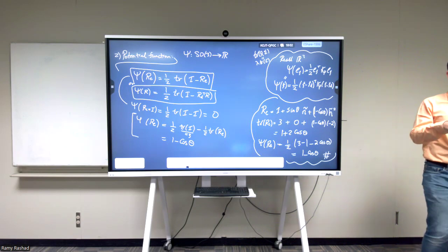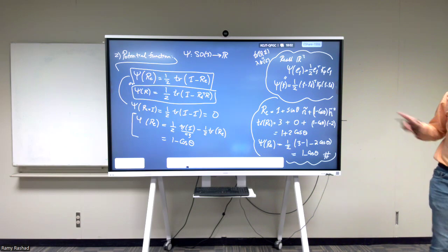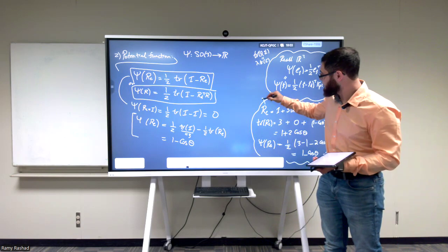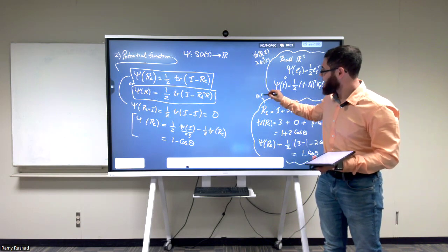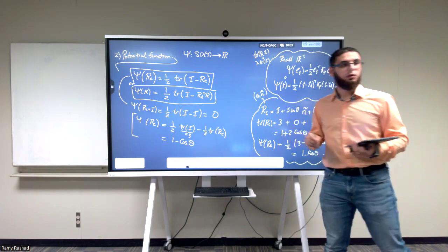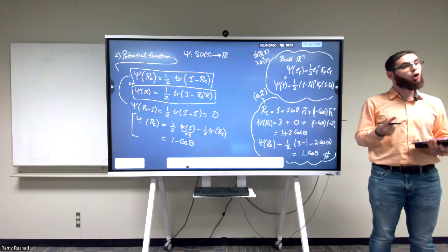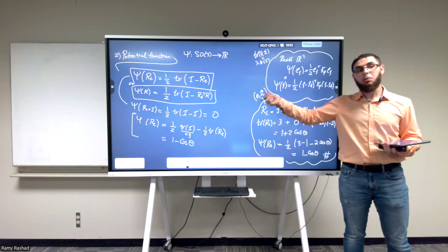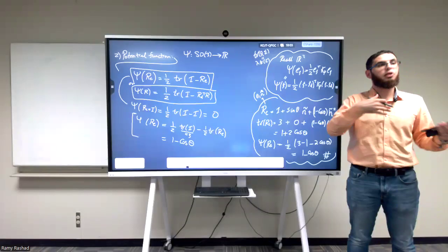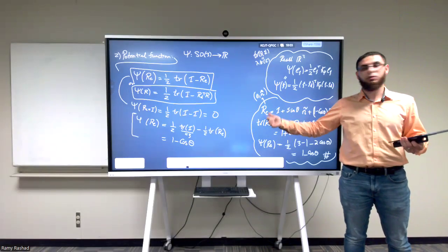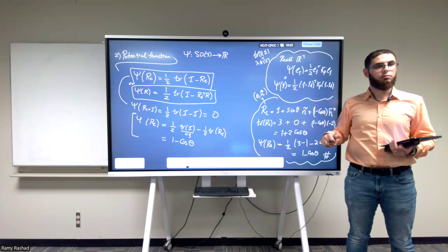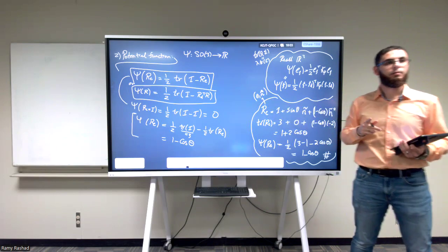Where does the theta come from? I'm saying that I can write R with any theta and any unit vector n hat. If we go back to when we looked at the exponential map, we can always write a rotation matrix with some theta. I'm not saying what the theta is, and I'm not saying how to calculate it. I'm just saying there is some theta that you can write any R as, you can transform it into it. Okay?